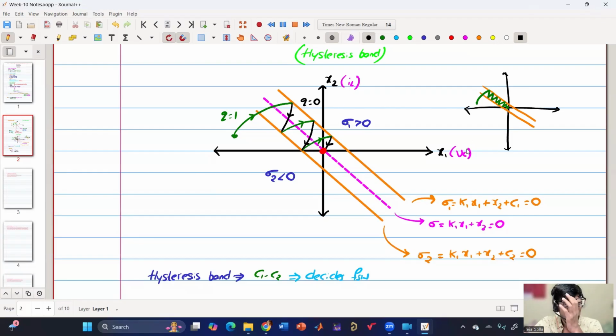Previously we had inductor current and inductor current reference. Whenever the inductor current hit the reference, we were turning off, and because it is fixed frequency, after a certain time period we were turning it on. But here it is not fixed frequency anymore. It is variable frequency because it is hysteresis control. So now we have assumed that we have peak current as well as valley current.